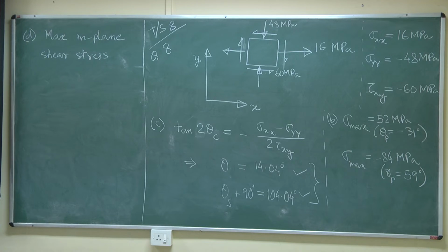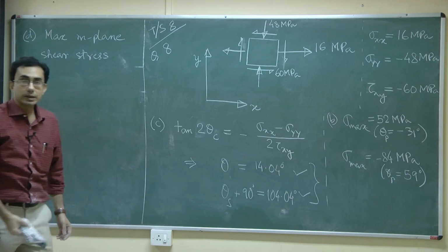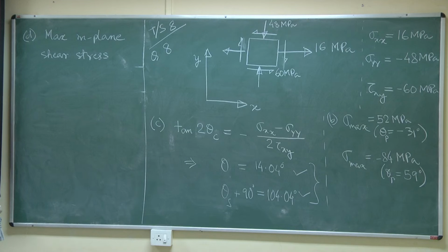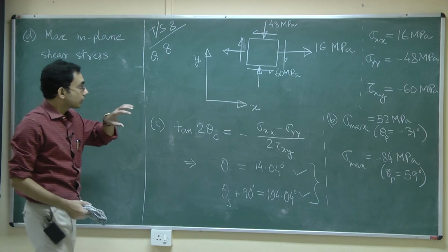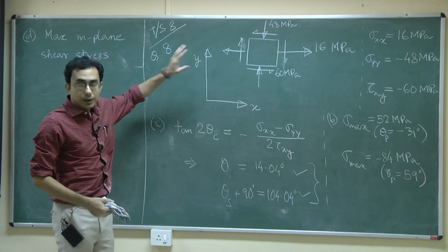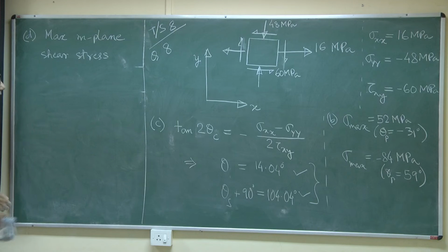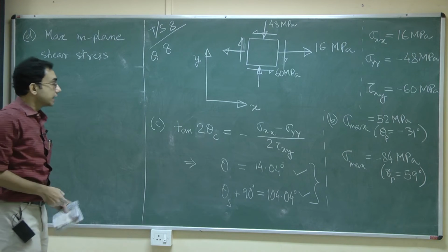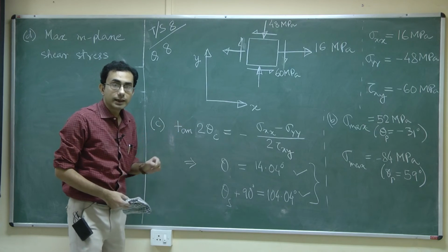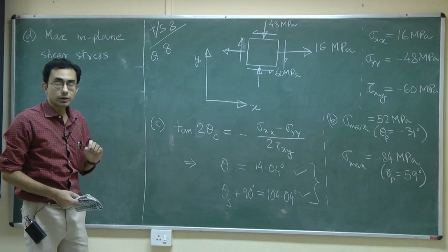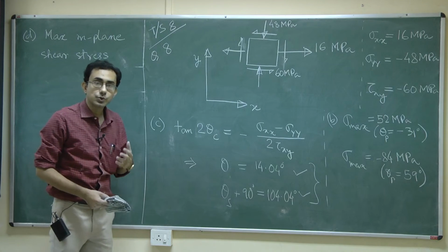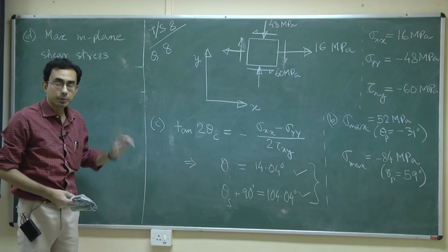From yesterday we have been discussing all along the reduced system which we have been referring to as the plane stress case. In this plane stress we are looking from the top down at a flat sheet, where the coordinate axes are oriented like x and y. But you also appreciate that there does very much exist this z direction, and we have mentioned that sigma zz is equal to 0, sigma zx is equal to 0 and sigma zy is equal to 0. So this is the special case which we are referring to as plane stress. All of these problems pertain to that.